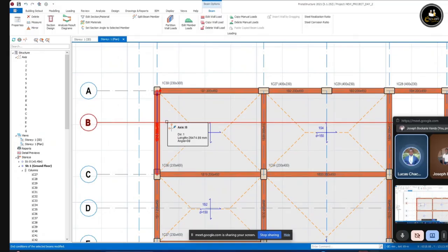But you want to at least relieve the fixed, you want to be more specific. Even if you design it like that, it will still be okay, but you use more reinforcement. So you want to come up with a more economical design by eliminating the hogging moments at the supports, because the moment at that support will be zero.